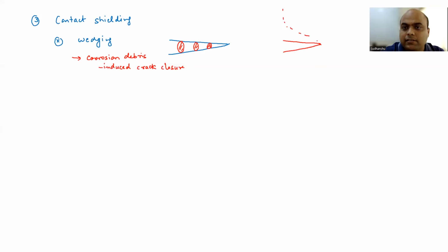We had these imaginary lines of force coming like this. And why were these deviating? Because they were finding air in this particular region in the crack, right? And air cannot transfer load. So these lines of force were deviating, leading to the concept of stress concentration.